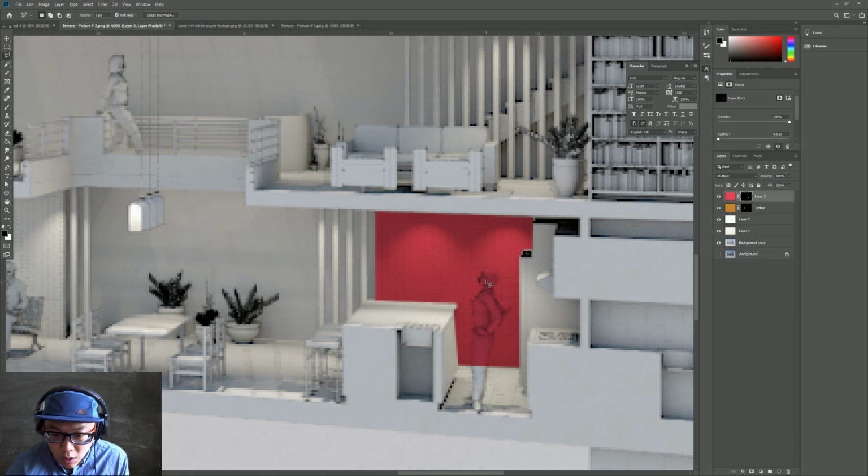So if I want to remove that person from the red, make sure that you're on the mask, because that's the color, that's the mask. You go there, and we're going to use the paintbrush. So when you're on the mask, now I'm just reducing. The shortcut is the little straight brackets. So you have that, and if you paint black, it will remove the red.